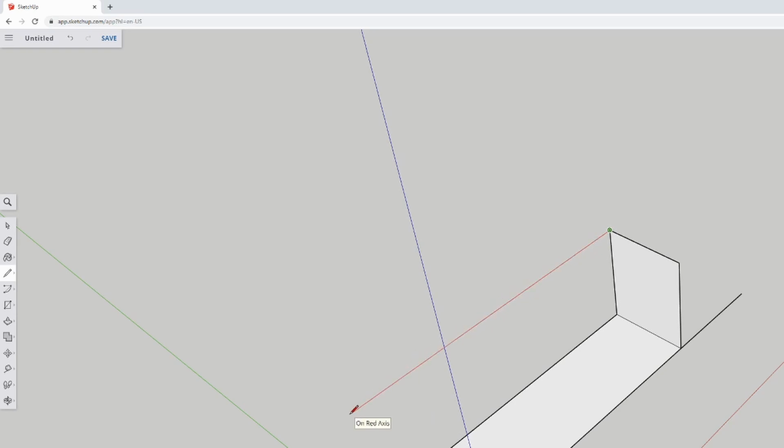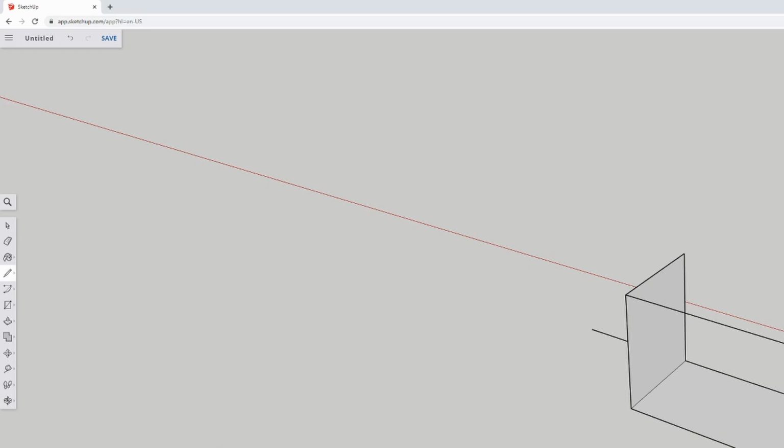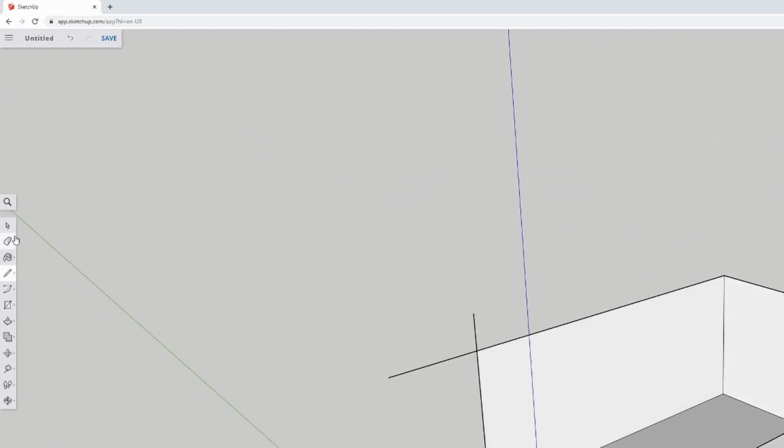But what I'm going to do is just drag and draw over the end point of where I believe it should be. Then I'll rotate the piece, hit escape to break the line waypoints, then select this corner down here, and then I can come up here to the edge, or in some cases I'll draw over it. And as I mentioned before, using the eraser tool, I can now chop off these extra bits.